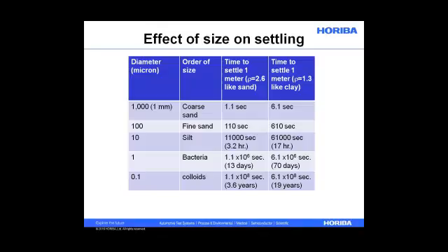And most people don't really want to wait that long or have a tank with a residence time of 20 years. It just looks like the ocean. So as you get to these smaller particles, this settling time gets really long, and that gets to be really expensive. So we want to make our small particles large.